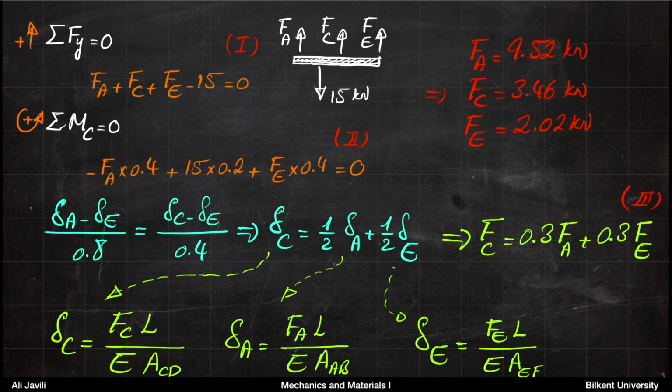All right, so this is another example of a statically indeterminate system. And if you compare this with the previous example, you sort of realize that they have similarities and they have differences. And in principle, always what you need to do is to find equilibrium first, and then you want your constraint second.